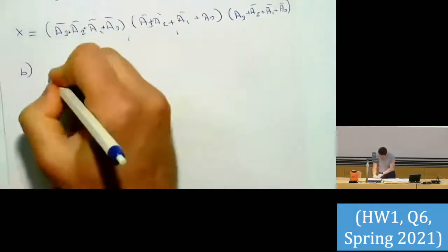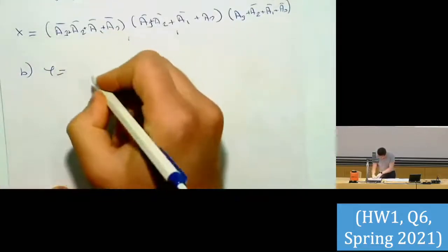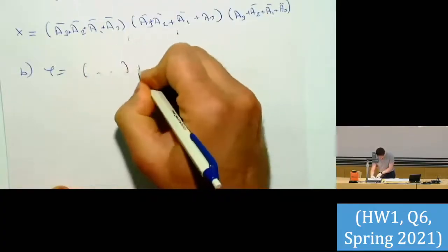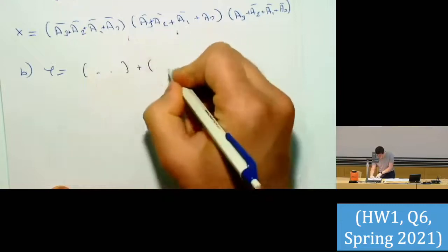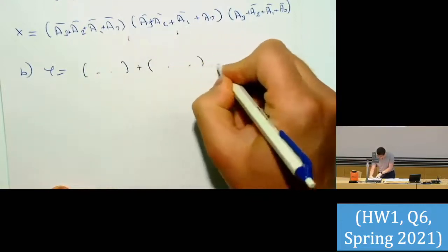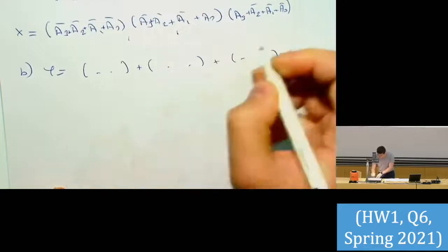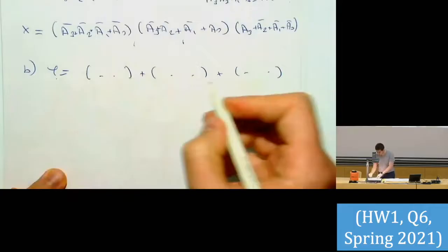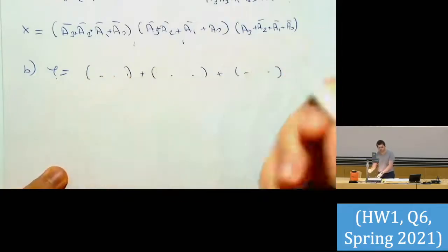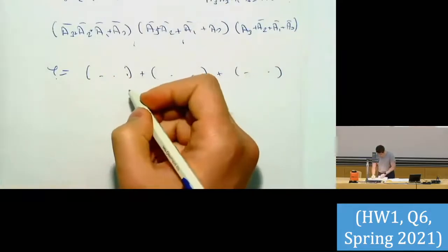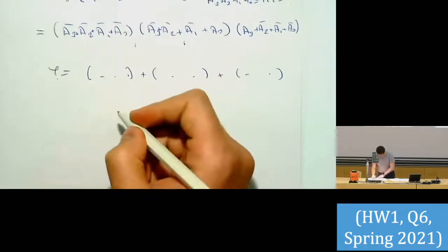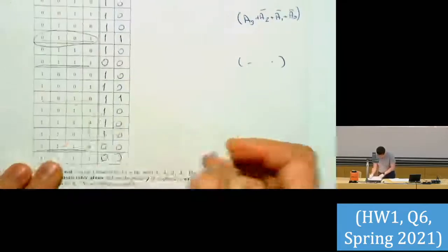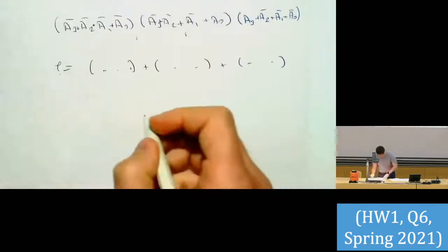And so what sum of products is, basically, I have terms, those terms are ANDed inside, and outside those are ORed. Right? So in other words, Y is 1 if one of these is 1, basically. So let's write it in that way. So to make Y 1, I have two options, either that or that, right?